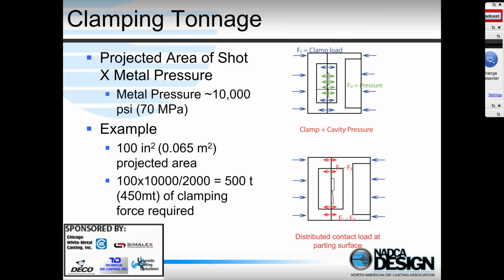So if you know the process we now use to calculate machine sizes, you can run that as a designer to make sure the caster is going to be using the correct machine size. For example, you run the calculation and estimate that the machine size is 500 tons, as we just talked about. The caster says he's going to run it on a much smaller machine. Ask them for their analysis. Ask them how they are planning to do that. If they want to run it on a much larger machine, say 2,000 tons, well, that's going to be a little big. It's going to run slower. Again, ask them about their calculation.